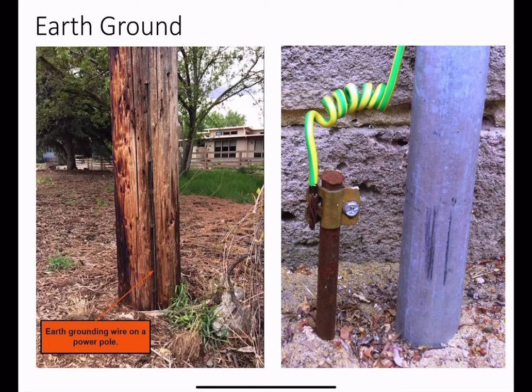So the building is also grounded. The building is grounded using a lightning rod on the top of the building, which collects all the current from the lightning strike, and through the conductor it dumps that huge amount of current into the ground, where it safely goes and diffuses without causing any damage.